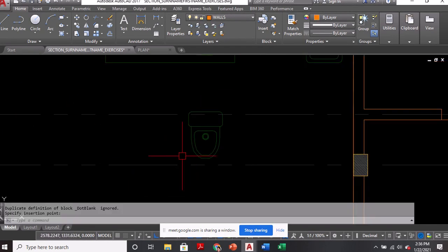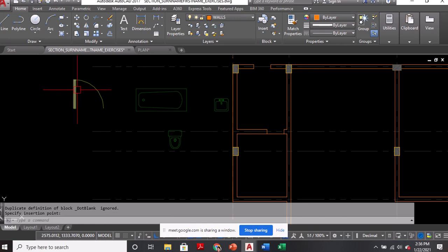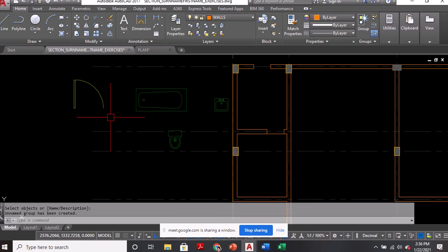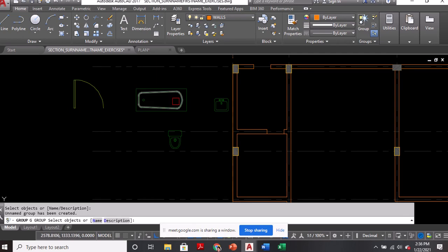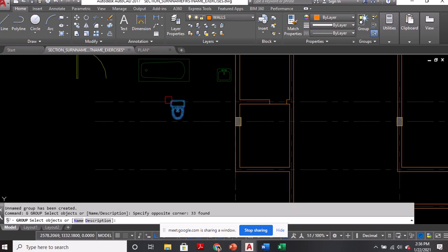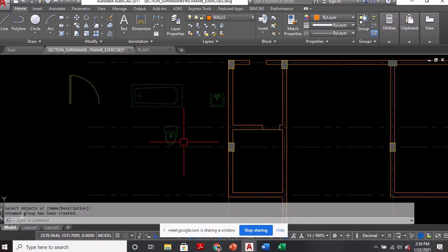Yan. Okay, afterwards, we need to fit this door template here. So, isa lang siya. Sorry, dalawang components sila. So, we have to group everything. Okay, so G enter, pick 1 and 2. G enter. Okay, so individual segments yan. For easy selection, you have to group objects. That's why, when you select them, isang click na lang po. Okay, there you go. Or I'll just move this one.